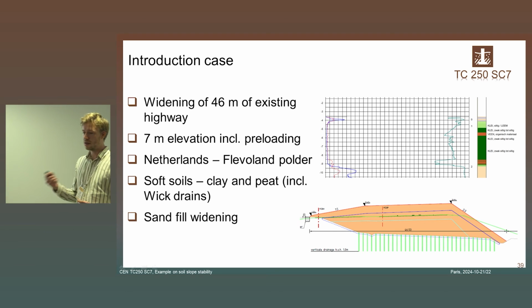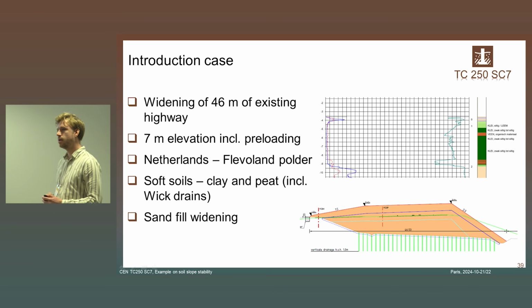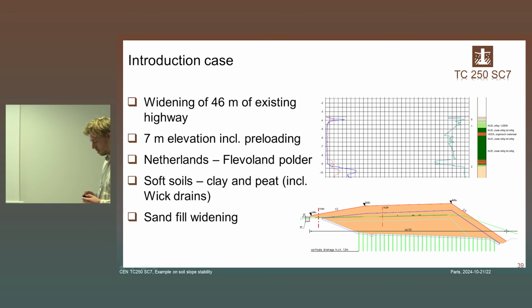So with every step of heightening the surface level, slope stability analysis must be performed to make sure stability is guaranteed during the entire construction process.